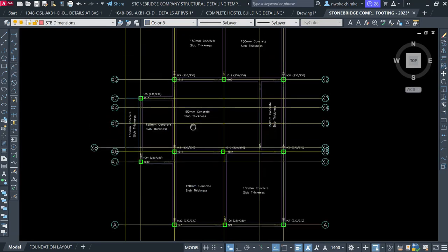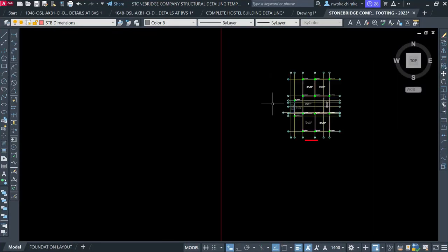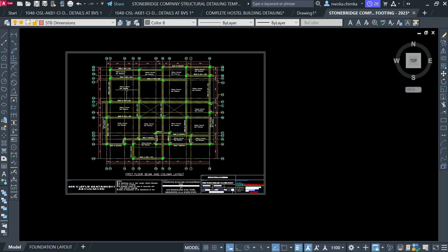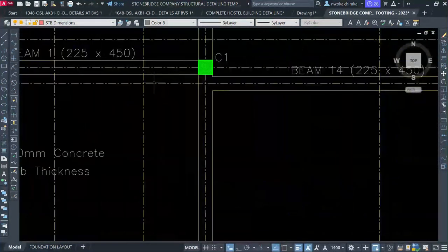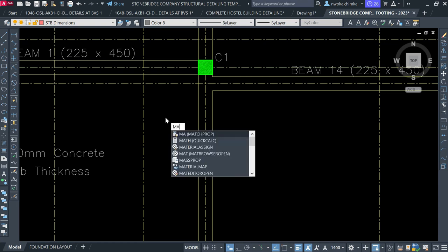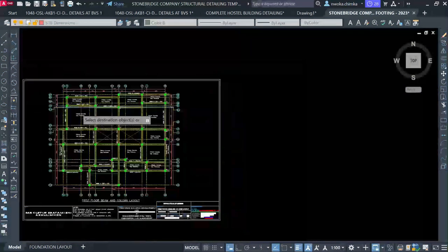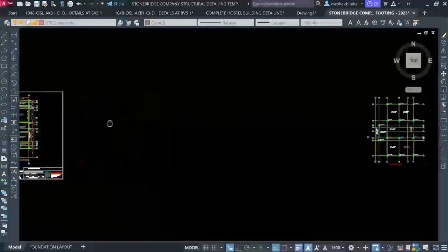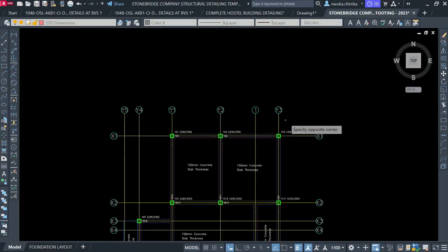As you can see right now, we now have this here. So again, right now, I'll look again. So I have finished placing this text inside that place. So what is next? The next thing to do is that this center line is shown as this phantom line. So I'll just say MA, which is match properties, and match this center line here. The reason for using this template is to make my drawing very, very visible and also to be standard. So I'll just go here right now and then match this.